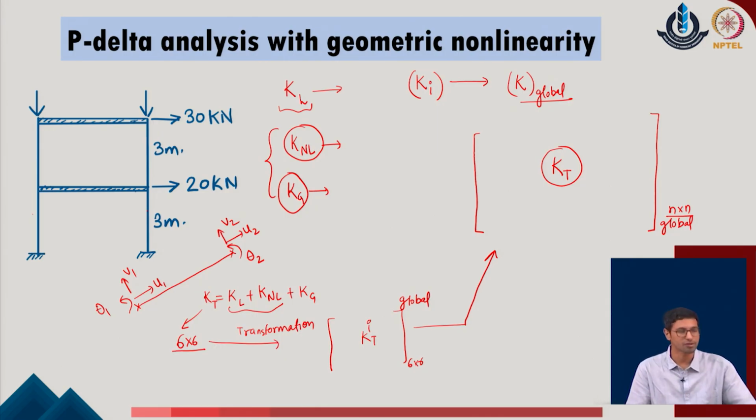Now, using this idea I will try to show how we proceed with the given problem. So, we already know the linear, nonlinear and the geometrical stiffness of the given system. In fact, we have also made a point that for the regular P-delta analysis, a user can reduce the nonlinear term which is coming due to the large displacement and only add the geometrical nonlinear term in the system, which is actually due to any kind of compressive forces in the given member, right. So, these are some simplifications which we make in the given simulations or problems, so that the analysis of the system can be done in a more realistic and faster way.